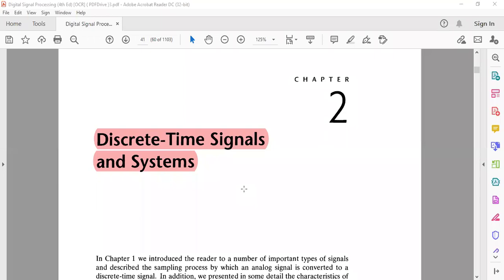We looked at the principle of sampling and the sampling theorem and said that since signals exist with a number of frequencies, the sampling theorem looks at the highest frequency component of the signal and uses that as a sampling frame, meaning you sample at a sampling frequency that is twice the highest frequency component of the signal that you have. So for example, if your signal